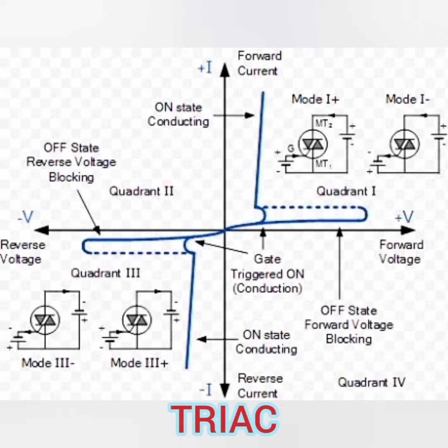Then this is the conduction state and blocking state of the TRIAC. Here the modes of operation, as I said, are given in quadrants 1 and 3. When the applied voltage overcomes the breakover voltage, the conduction takes place. Further, the turning on of the thyristor is done.